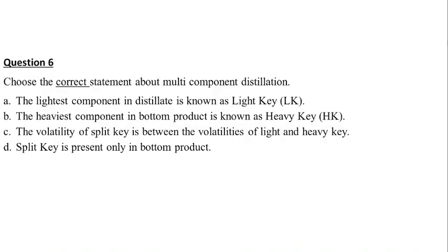Moving to the next question, choose the correct statement about multi-component distillation. The lightest component in distillate is known as light key. No, it is not a correct statement. The lightest component in bottom product is the light key. The heaviest component in bottom product is known as heavy key. This is also an incorrect statement.